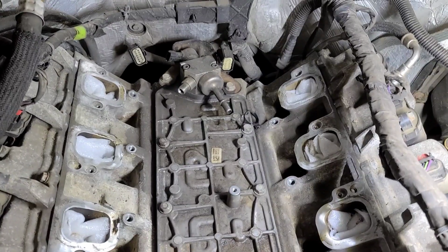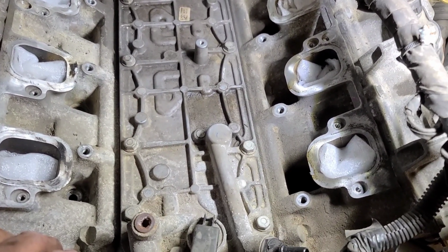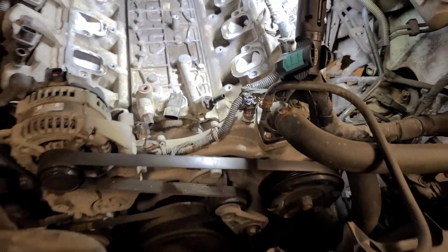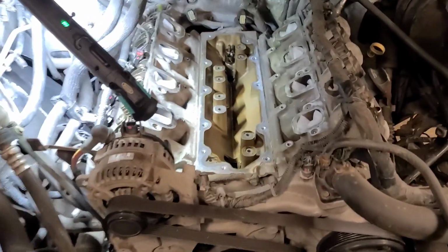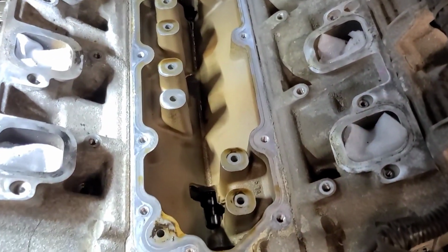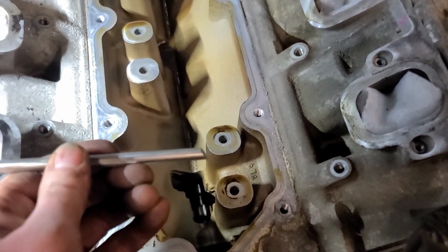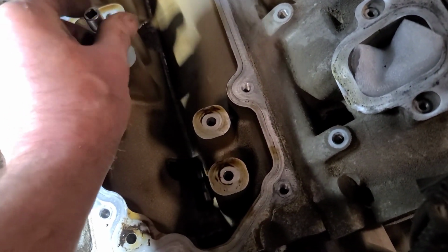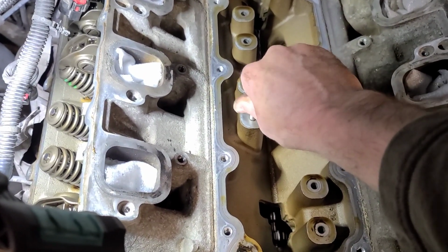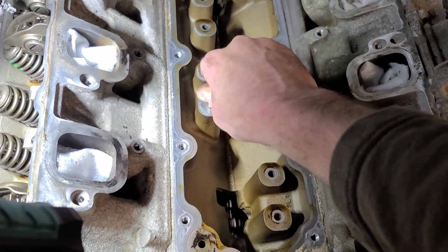Now we have to take the high pressure pump off the back, and of course, if this fixes it, we're going to end up having to put all new injector seals in here. I should have some left over from that job. So there's the valve lifter oil manifold off. This is the passage here. I made this little tool based on a YouTuber's description. It's got a 45-degree angle cut on the end of it. It goes in and contacts the side of the lifter.